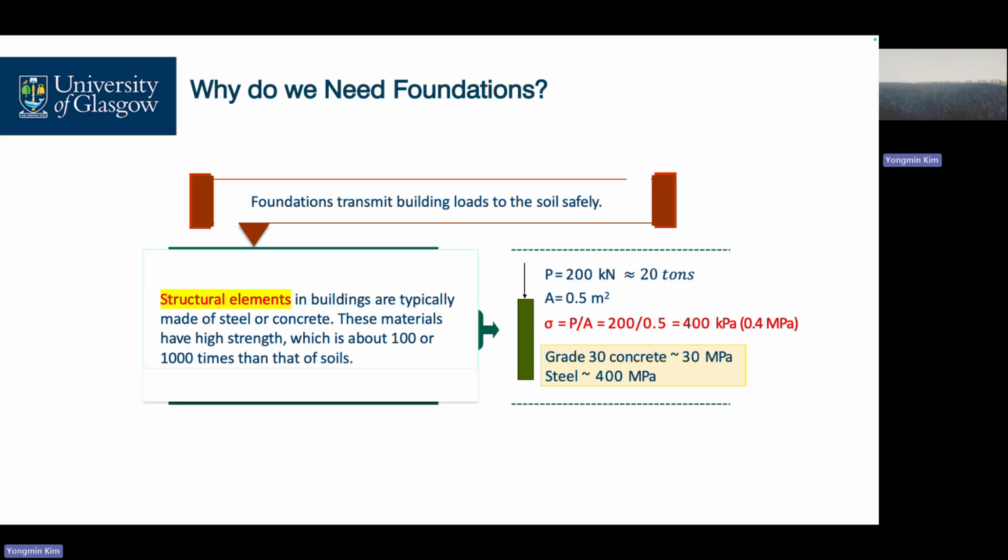Sometimes we use steel pipe, and the strength of steel is much higher than concrete. It means we don't worry about the material itself. Let's consider this is the pile, very strong. The problem is always the soils. Soil fails first. That's why the role of our foundation is to transmit our building loads, and our soil should have strong enough bearing capacity.